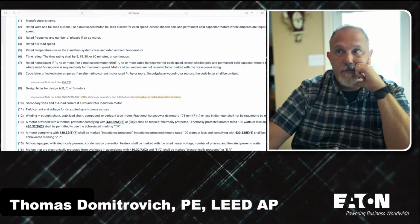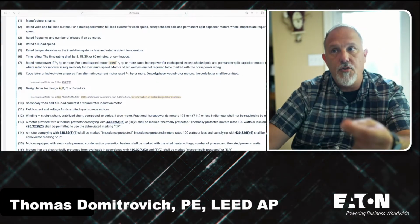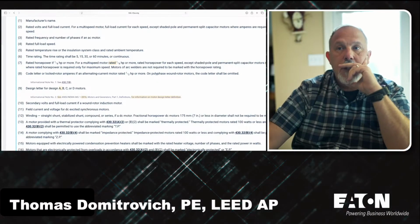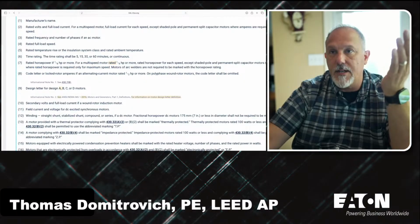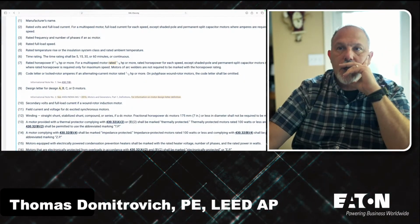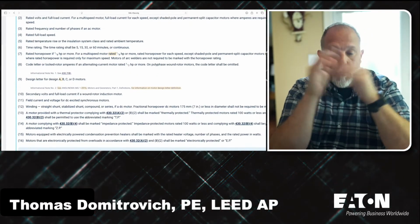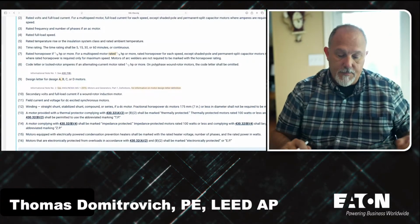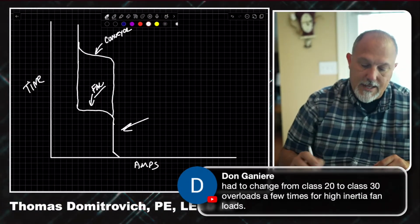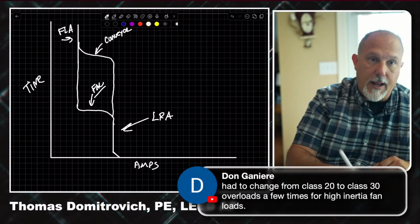The time rating, this would be like your intermittent duty. How long can you run this motor continuously, or it'll be a continuous duty type of motor. Rated horsepower, whether it's 100 horsepower, 50, 30, whatever. Code letters for locked rotor amps. Remember the locked rotor amps? We talked about that. That's my locked rotor amps, and this is my full load amps.